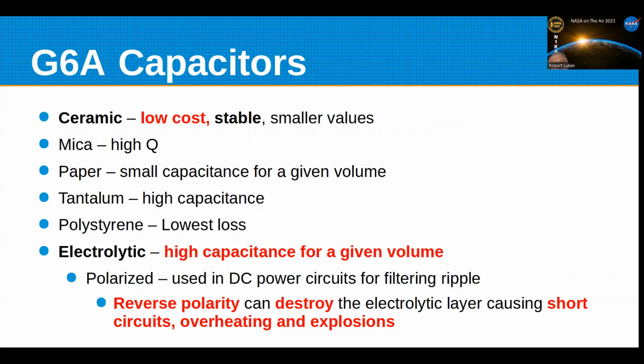They come in the smaller values, from a few picofarads up into the microfarad range. And then we have electrolytics, which are used if you need high capacitance in a given volume. These give you many microfarads. You can even get supercapacitors that are in farads and relatively small.